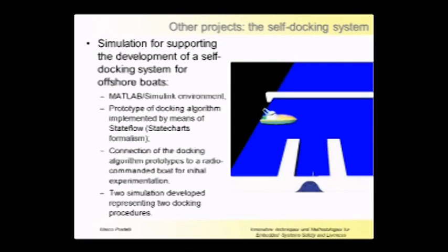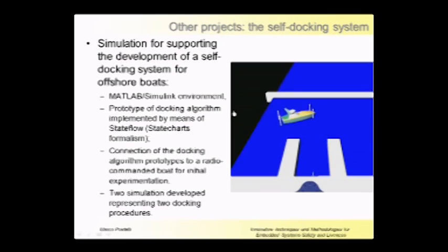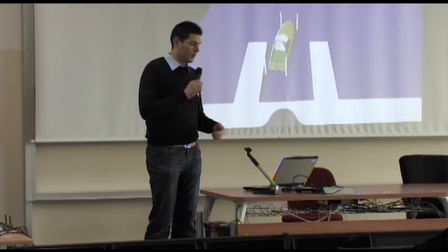I also worked on another project. In particular, this one is, sorry for the resolution, a simulation that I developed for a company that was working on a self-docking system for offshore boats. I developed this simulation in the MATLAB and Simulink environment, and I provided two prototypes of the docking algorithm that is driving the boat by means of the Stateflow component of Simulink, therefore by means of Statecharts.